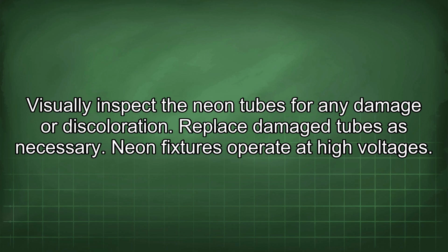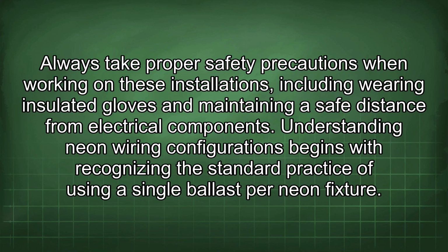Neon fixtures operate at high voltages. Always take proper safety precautions when working on these installations, including wearing insulated gloves and maintaining a safe distance from electrical components. Understanding neon wiring configurations begins with recognizing the standard practice of using a single ballast per neon fixture.